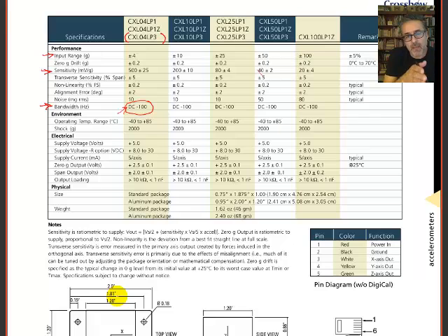So this device that we have here is sensitive to a constant acceleration. A lot of accelerometers are not. This happens to be one type. So that's something to keep in mind in some applications that you might run into. Sometimes you need to measure that 0 frequency. You need to detect G, when you actually have a constant gravity acceleration. Sorry, not necessarily constant gravity, but just constant acceleration. But it turns out gravity is a constant acceleration. So these accelerometers can actually detect your g vector, which is a nice feature to have.